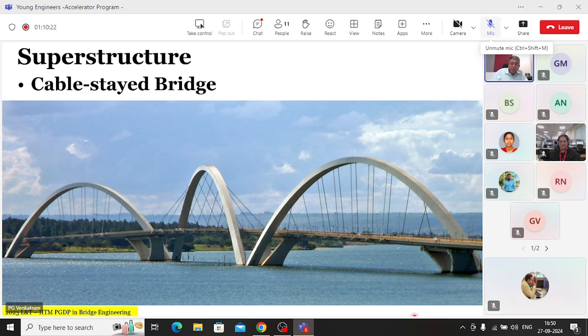That is, I have a feeling, the angle of the image. If somebody took a picture from this side, you'll possibly find that almost all the cables from the side view look vertical. The angle of the picture is such that it makes one think that they are. If you see this example, they are nearly vertical. It's just that angle. But you're right in saying that this is a cable stayed bridge. The only thing is the pylon is not vertical. And why is it not a suspension bridge?